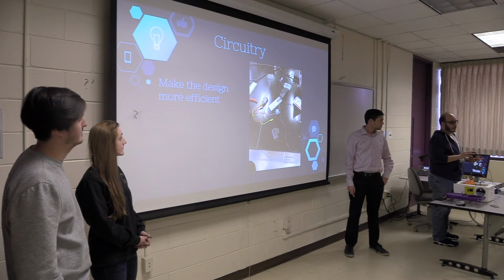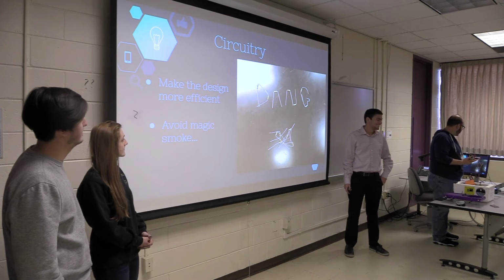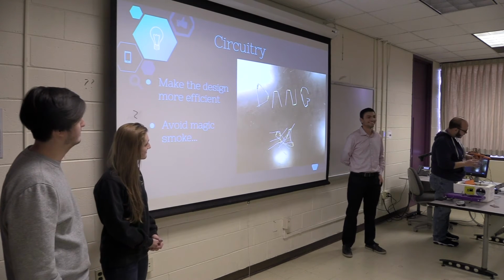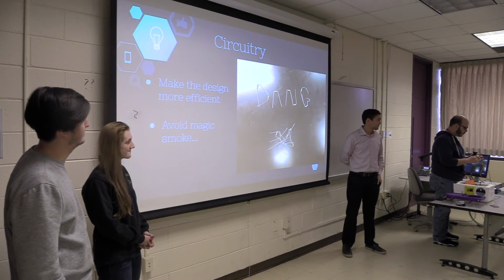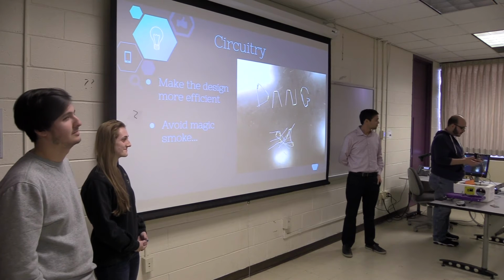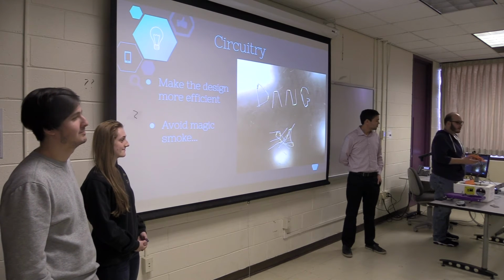We could keep it turned on for about 3 minutes and then magic smoke. And as anyone knows, magic smoke, not good. We were able to find that a 5-volt power supply for the lock itself, which is actuated and controlled here by the Raspberry Pi, allows it to operate almost indefinitely without magic smoke.